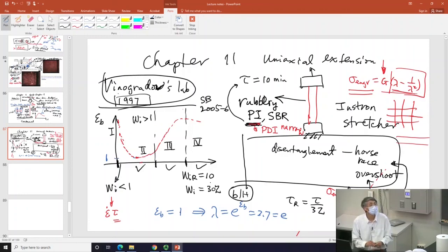So this horse race just cascades. It's like an avalanche. Once it starts, it does. Remember, I even had a great deal of comment about the Considère criterion about necking. This disentanglement could continue for a long while, and at some point, the structure is just no longer able to sustain itself, and some part will start to fail.